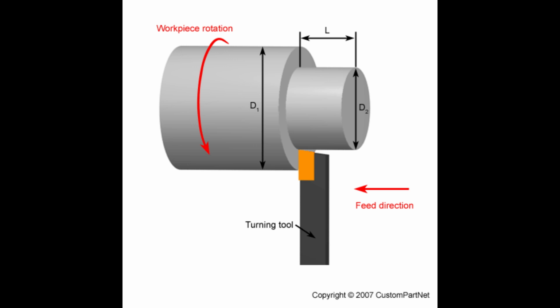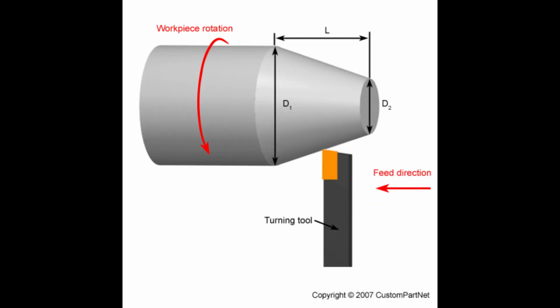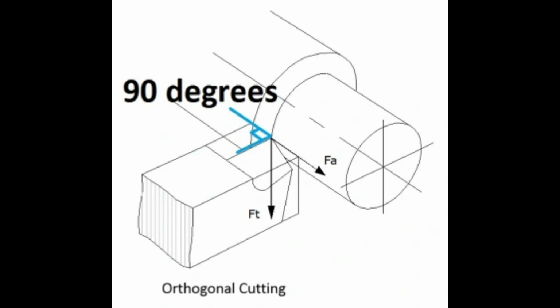The nearest edge to the direction of travel of the tool should be set so it is at 90 degrees to the axis between the centers of the lathe, head and tail stocks. This is not only so the tool can cut cleanly and truly, but so the edge also leaves a square face. It also means that the cutting edge has the lowest possible surface area working the material of the job, keeping friction to a minimum, and helps prevent premature tool failure and assists with keeping the work cooler. It also helps prevent chatter and allows for a quieter cut.